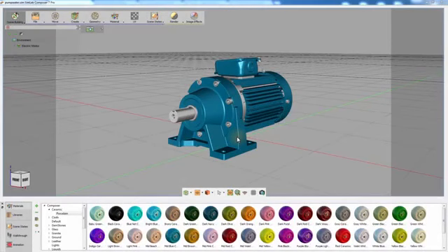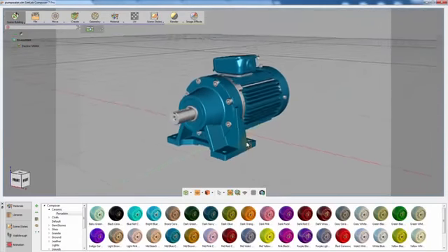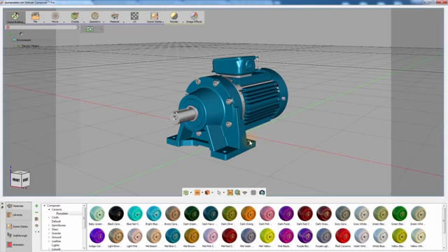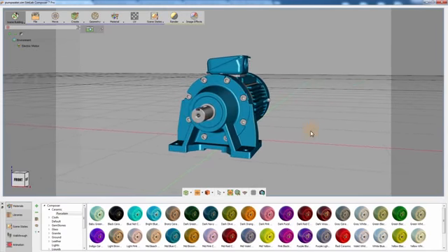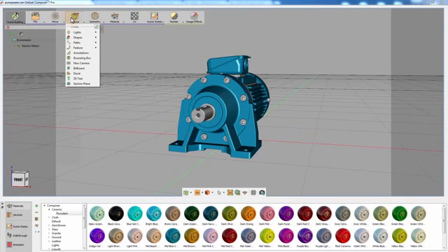In this tutorial, we are going to talk about adding annotations and measurements to your mechanical design in SimLab Composer, and how you can manage the measurements to create a professional presentation that facilitates communicating and sharing your design. Go to the Create menu and select Annotations.